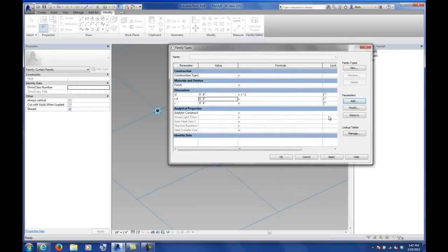When I enter R-4 into the formula box, it thinks it's looking for parameter R minus 4. So avoid mathematical symbols. And also, if you're going to name things with numbers, always make sure there's no space. Because if there's a space, it'll start thinking that you're trying to do something with the number 2 instead of making that part of the name of the parameter. So there are a lot of pretty neat options there.